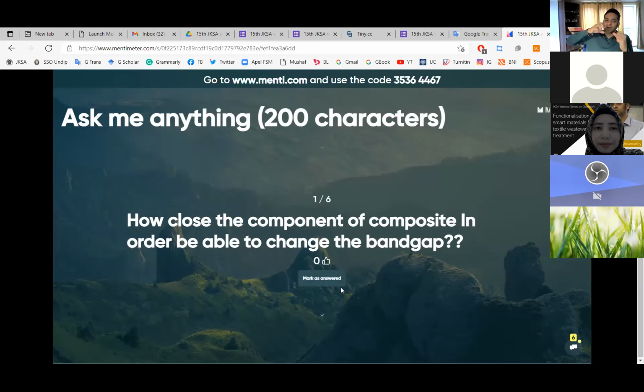So we cannot have a system where the band gap of one is 2 eV and the other one is 5 eV. We cannot do the band gap matching, even though we put a lot of nitrogen to create the vacancies, and it won't work because the idea of defect engineering is you either use oxygen vacancies or nitrogen vacancies or interstitials, which is created by heat or through the plasma method or through the chemical methods.